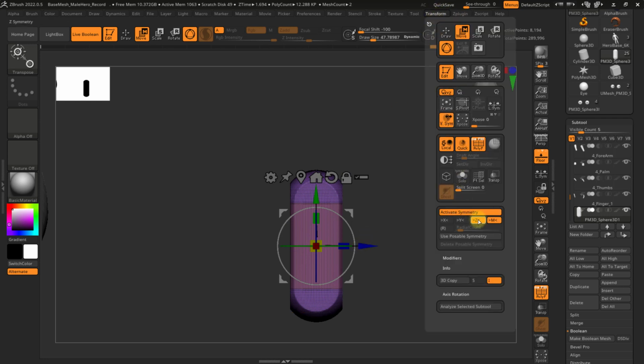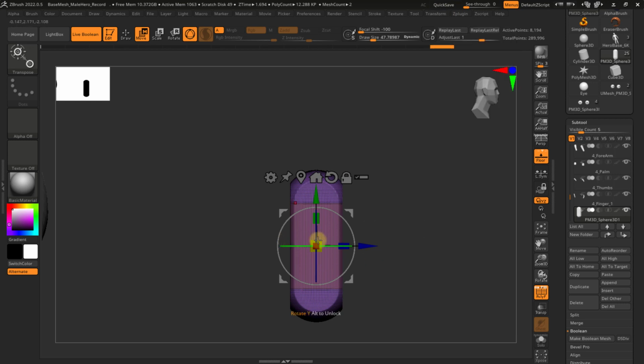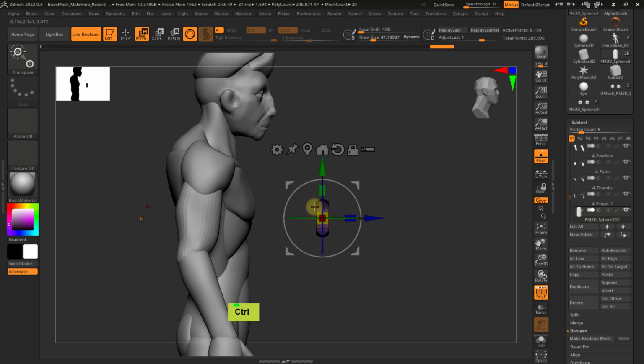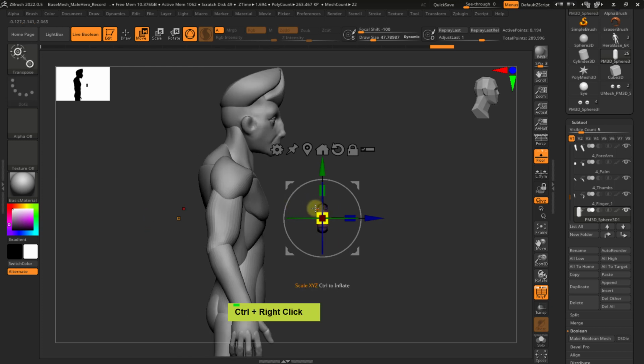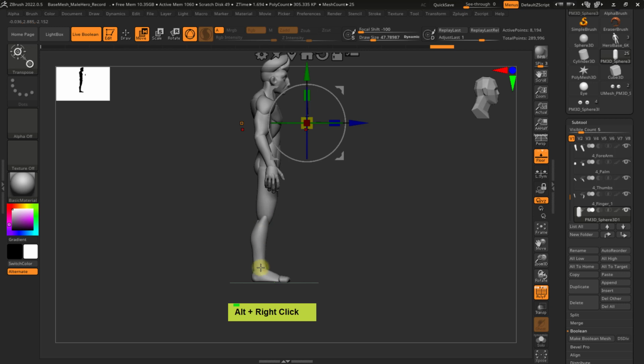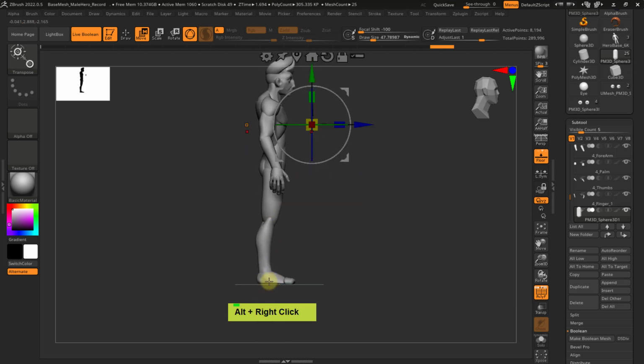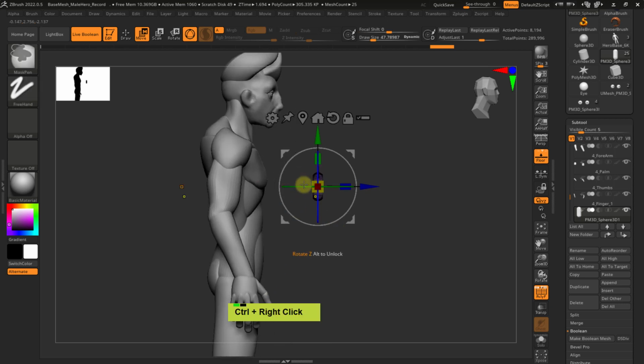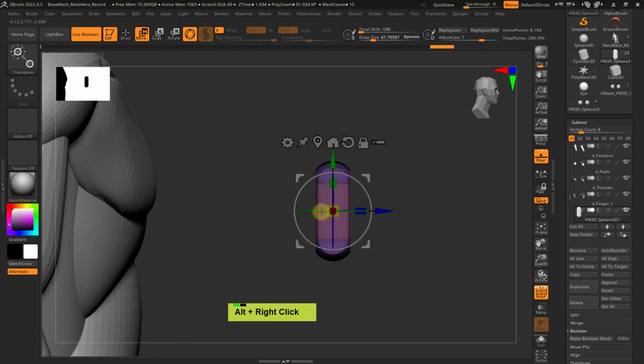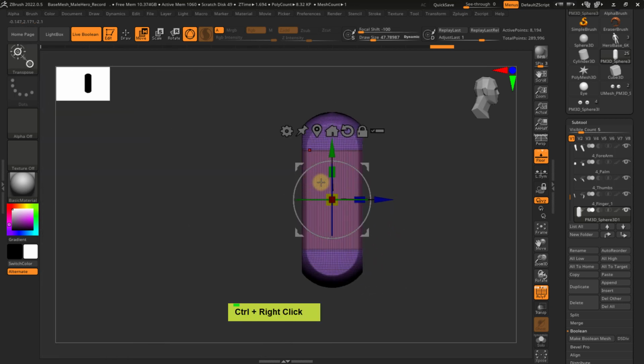Clearly, we have Z on, activate symmetry on, and it still doesn't know where this point is. Look, if I'm walking the distance, my brush is traced on the back of the figure, and the reason is it follows the center of the scene. It follows the very center of the whole set, instead of respecting the actual position of the model.